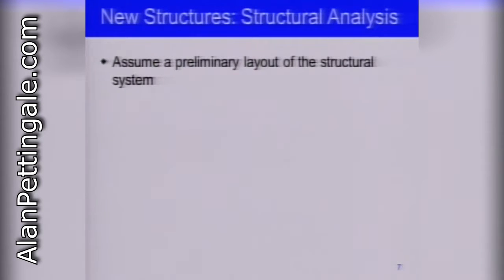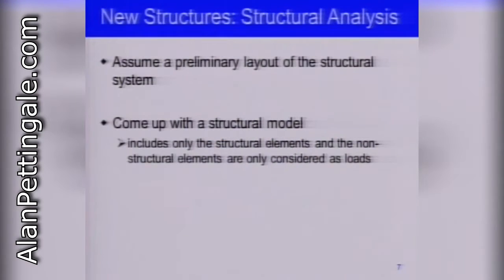So the path to designing a new structure is essentially you assume a preliminary design, you come up with a structural model for that. We simplify things, we keep only the structural elements; the non-structural elements are only included in the simplified model as loads.